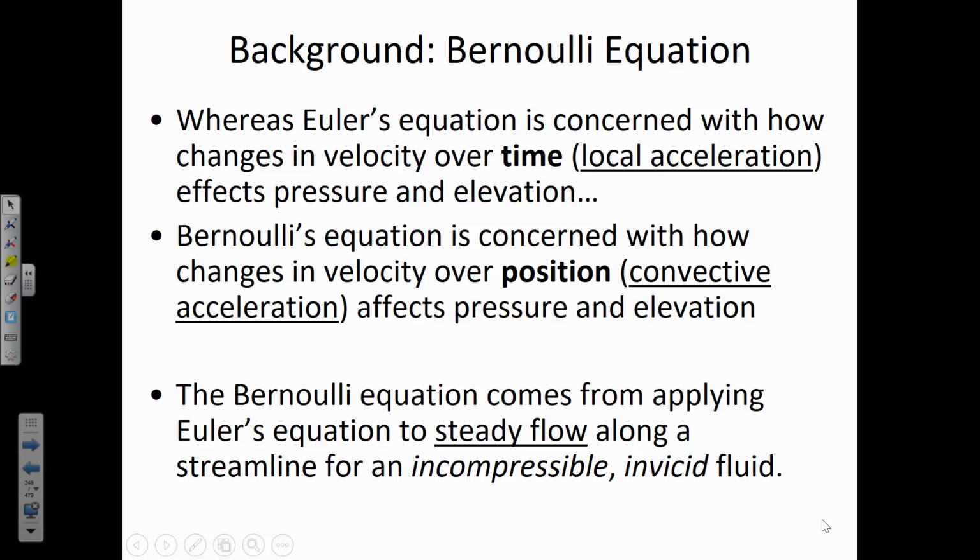Gases, on the other hand, like air, are highly compressible. So what that means is that sometimes we'll have errors in applying Bernoulli's equation if, in reality, the fluid is compressing a little bit. Then there may be some changes in pressure that Bernoulli's equation isn't accounting for, because built into Bernoulli's equation is the assumption that this fluid we're applying the equation to is incompressible. The fourth limitation or assumption is we're assuming that the fluid is inviscid.